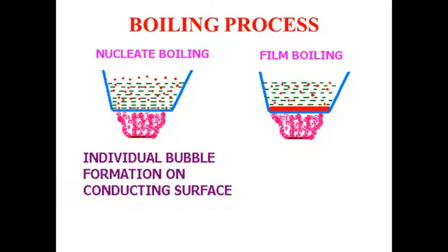Gradually, some liquid particles get overheated, attaining above the sensible heat gain, and they receive the heat available in the vicinity, and with this excess heat, receiving the latent heat of vaporization, they turn into tiny vapors, and these tiny vapors, when they try to move up across the bulk of the fluid, collapse and spread the heat across the bulk of the fluid.